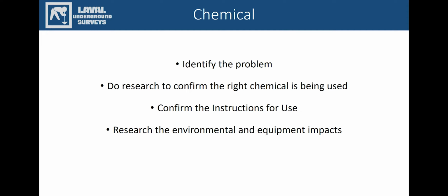The structure of the well matters. Is it based in limestone or rock? This might affect the chemical's efficacy and the dosing requirements needed.